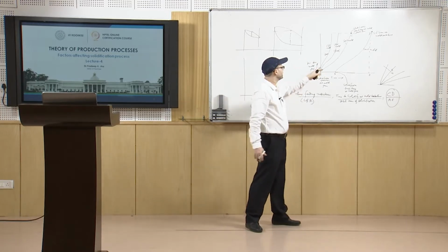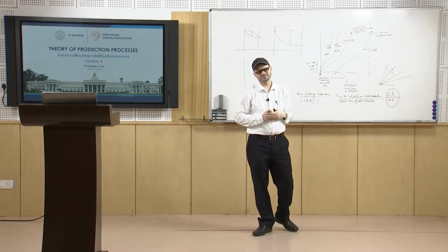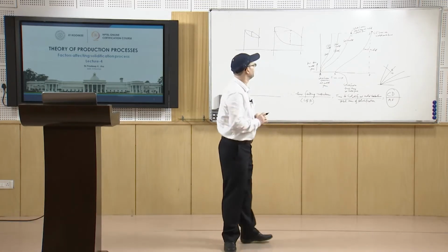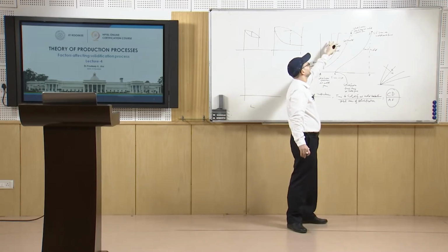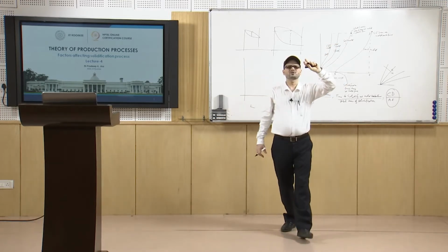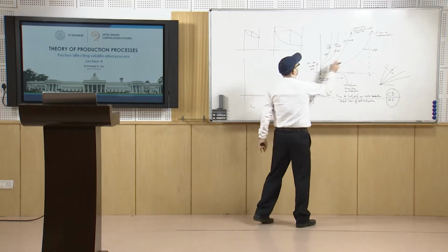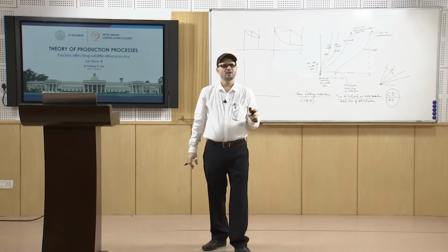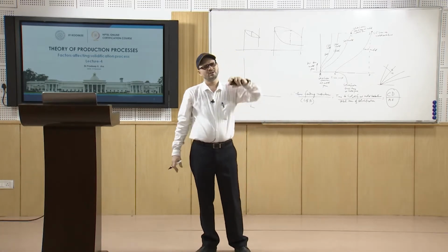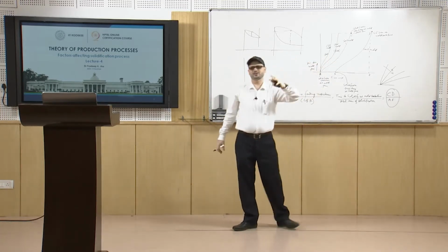It starts quickly at the mold wall, and because of the large heat extraction rate, a gradient develops, and the separation or width between the lines will be smaller. So, this is how it shows the effect of the molding material, whether it is a chill mold or a sand mold, these freeze wave lines will be changing.